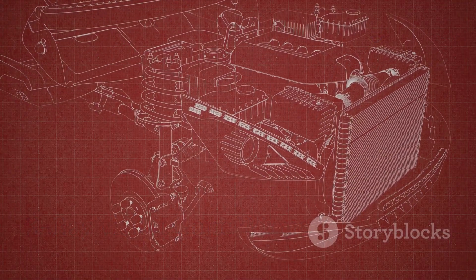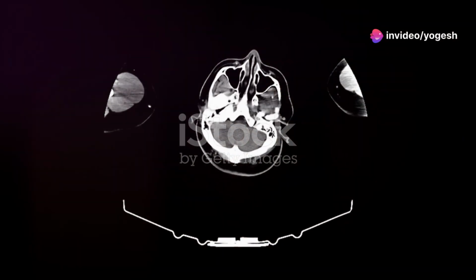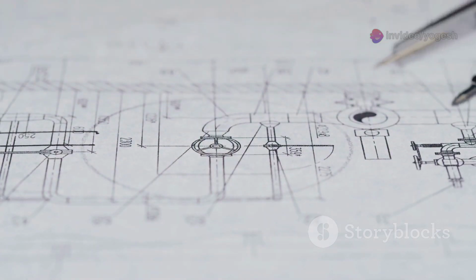Sectional views reveal internal features, but only if done right. Choose cutting planes that show the most useful info. Don't just slice down the middle. Use correct hatching to distinguish parts. Never hatch everything the same.